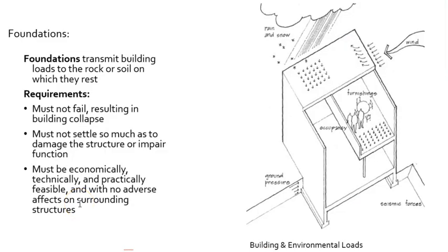So the purpose of the foundation is to transmit the building loads to the rock or the soil on which they rest. In general, the requirements of the foundation are obviously that they must not fail, resulting in a building collapse. They shouldn't settle so much as to cause any damage or impair the functionality of the building, and they must be economically, technically, and practically feasible, with no adverse effects on the surrounding structures.